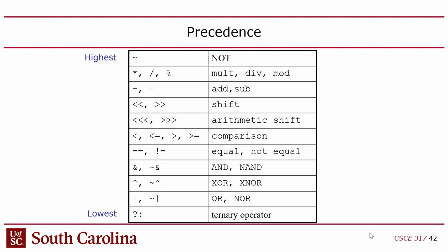So they might say, wait a second, if divide is so hard to make in hardware, why do we have a divide symbol here? And presumably if we use this in a module and synthesize it to hardware, it'll create a divider circuit, right? Yeah, it will, and I've tried this once. For 611, I put it in some Verilog, and I synthesized it, and it ate up the whole FPGA, just that one operation. And I don't even know if it worked.